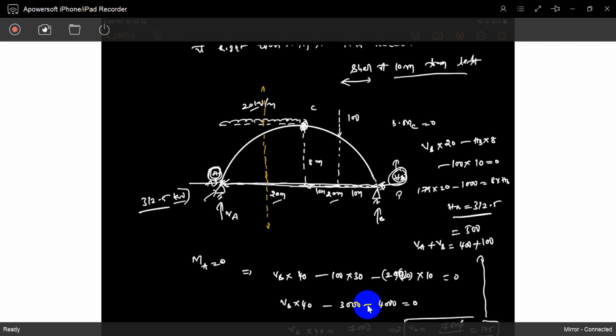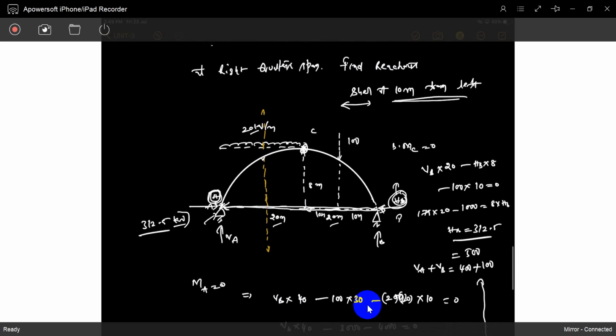Once you got it, what is the bending moment at that location? He asked for shear at 10 meters, directly from 10 meters from the left support, but I ask for 20 degrees with respect to the crown. The position of that section makes an angle of 20 degrees with respect to the crown. I ask it the same as an arch.